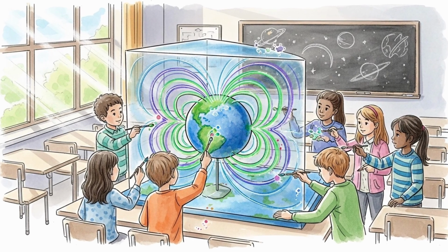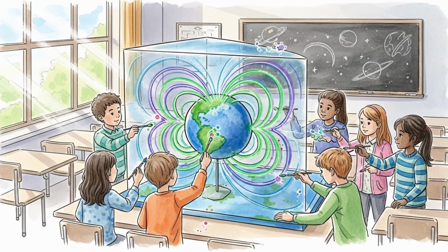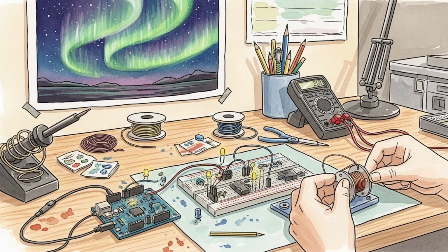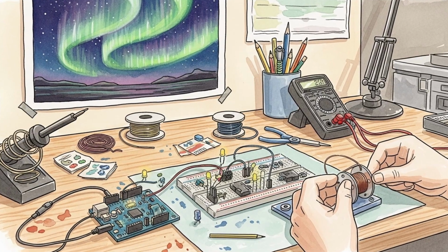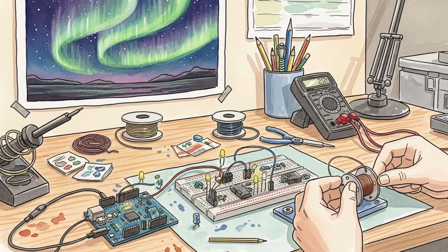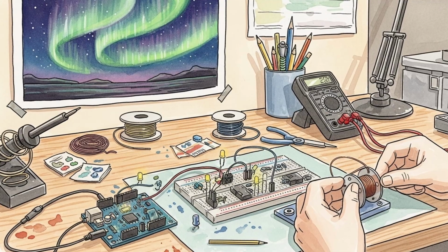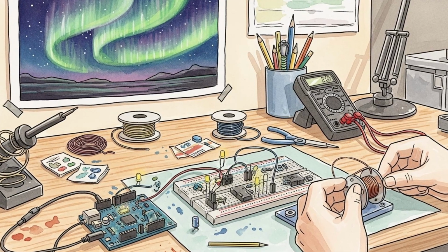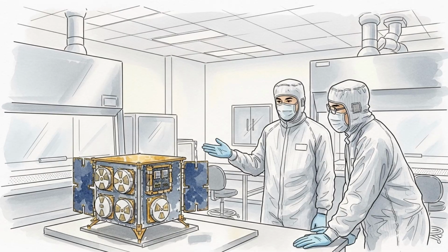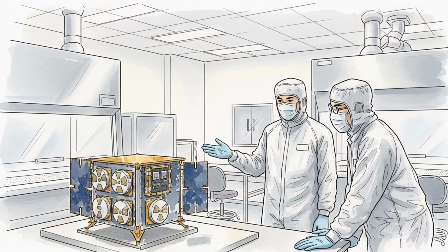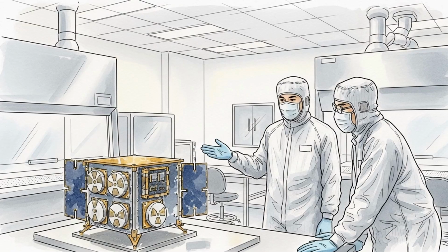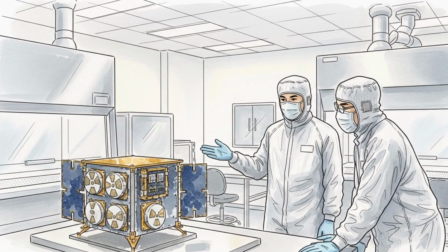After a storm, operators review performance. They check error rates, lost lock events, time offset logs, and power alarms. They compare behavior to previous events. They reset thresholds to normal values, remove temporary routing changes, and restore planned maintenance windows. They analyze where holdover was sufficient and where it was not, and they adjust oscillator classes or distribution design for the next season.